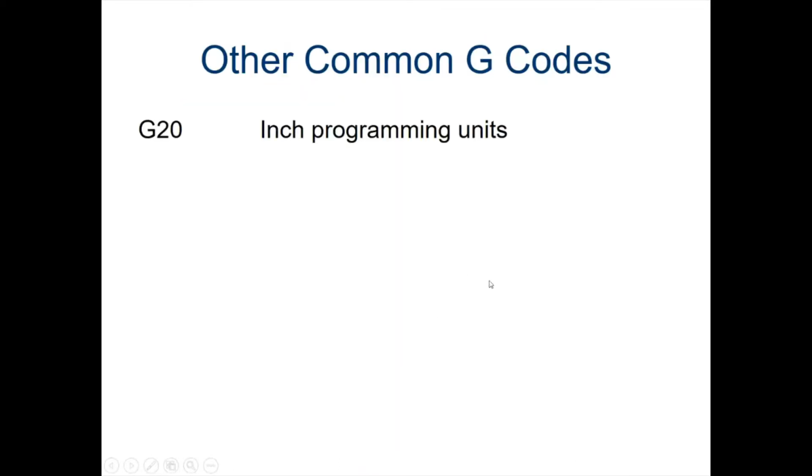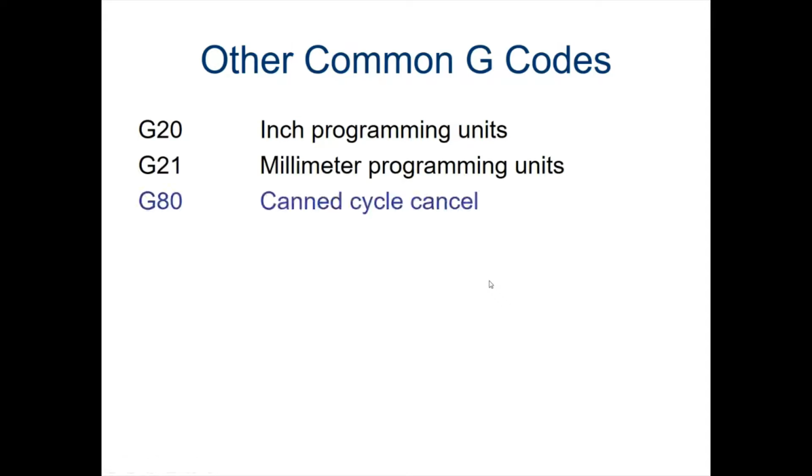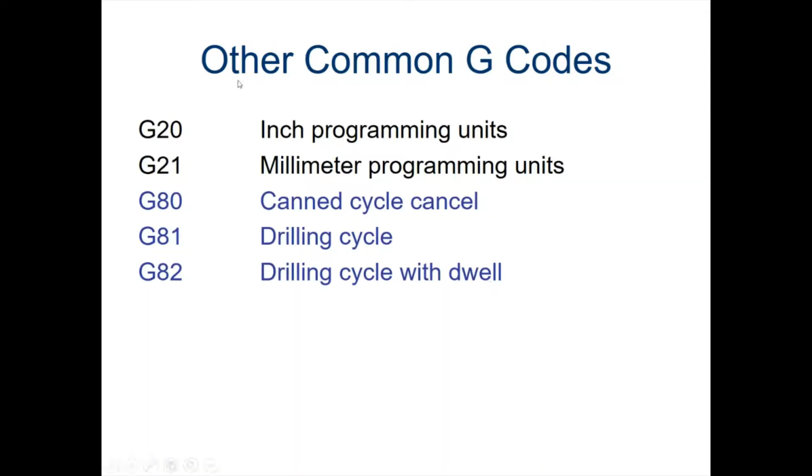Okay, some other G codes that you'll run into. We'll talk about all these. I'm just going to click them all up here on the screen real quick. So we have G20. That is just basically what units are we using. Are you putting everything in inches or are you putting everything into millimeters? If I use inch, I want G20 in there. That's, again, a beginning-of-the-code type of thing that I'm going to put early in my program to specify what I'm using before I start actually referring to coordinates. And then G21 says we're going to be in millimeters. Those are really the only options that we have. There may be a G code for other units besides those, but realistically, millimeters and inches are what we're going to use.